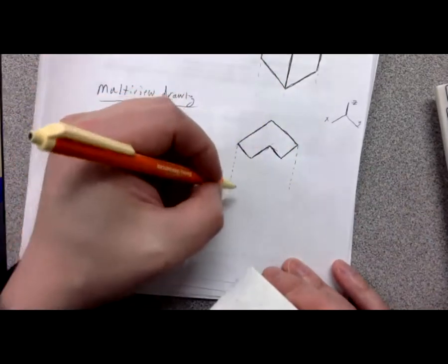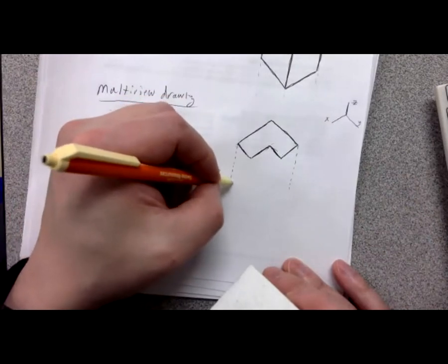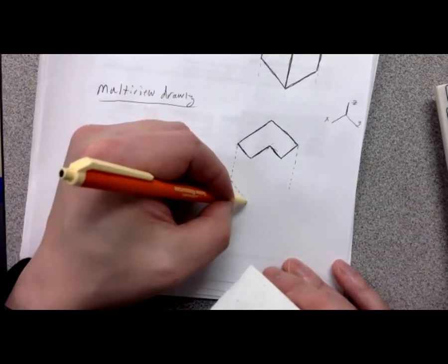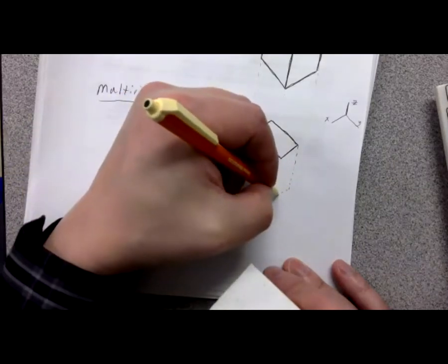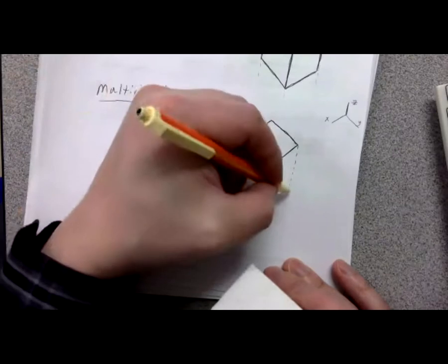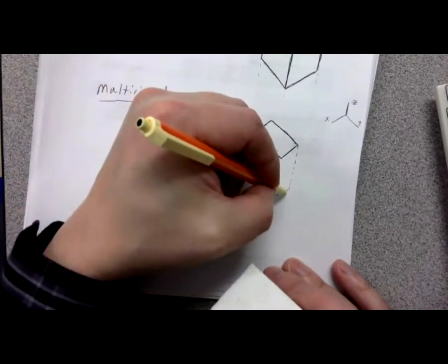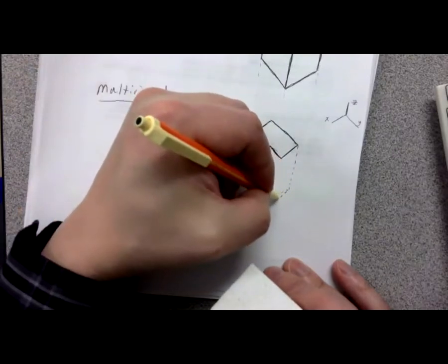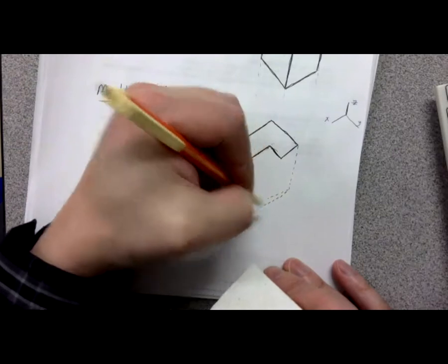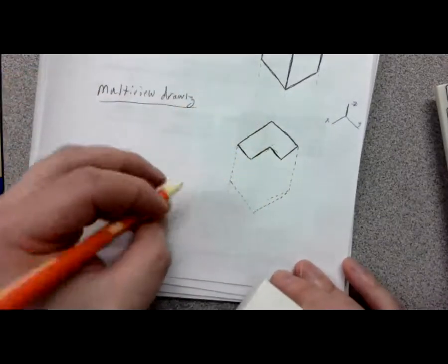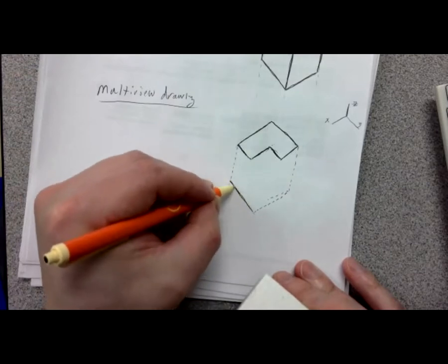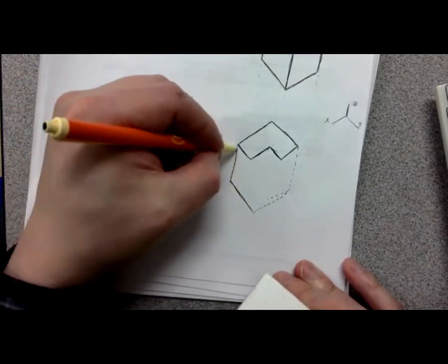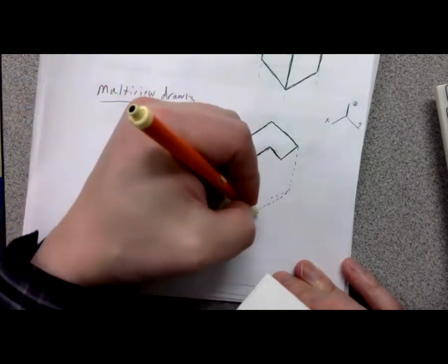And I'm going to say probably from right about here, I'm going to dot in the Y direction out a little ways. And from this point here, I'm going to dot out. That's off a little bit. Dot out in the X direction, and try to find their intersection. And once I've found those intersections, I'm going to go back and darken those all in. That kind of gives me the overall outline for the shape.